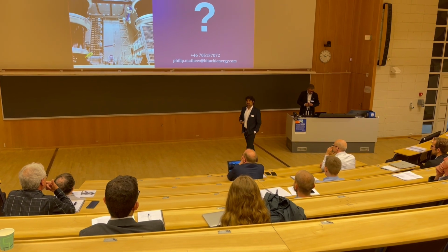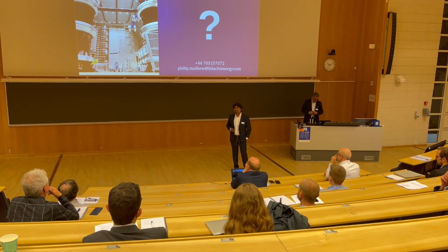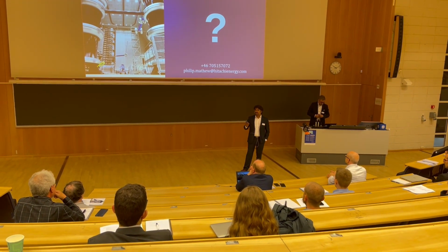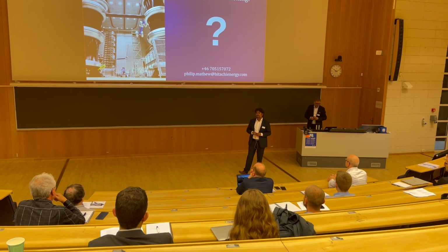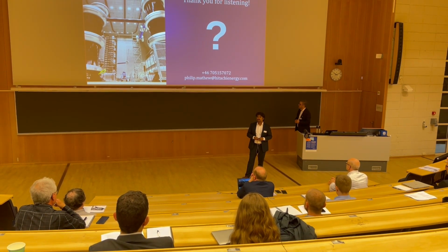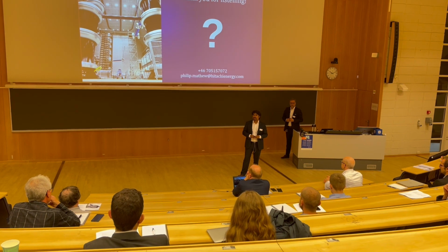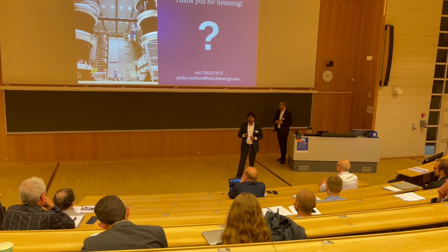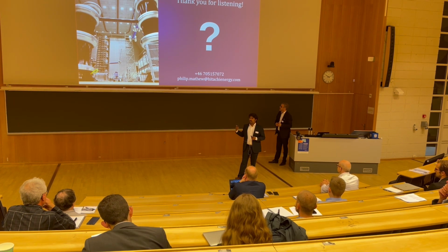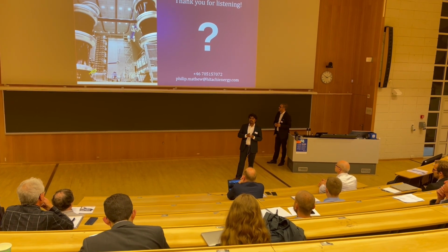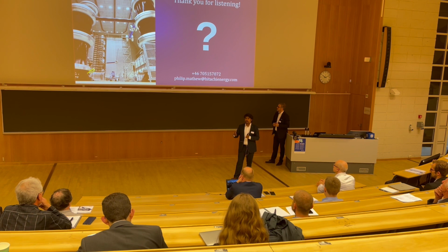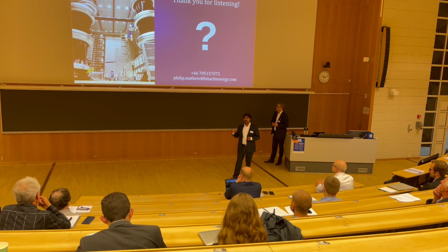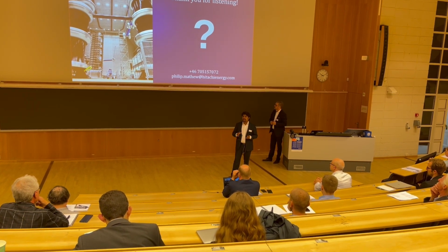Thank you for the really good question, and thanks for the presentation, by the way. So two things. First, yes, these issues that we will face in solid-state transformers are very similar to what we faced in the 1990s with inverter-fed drives. The difference, however, is that when we talk about SSTs, we talk about different rise times and different frequencies, and that's the reason why we thought 2 microseconds is a good bet.